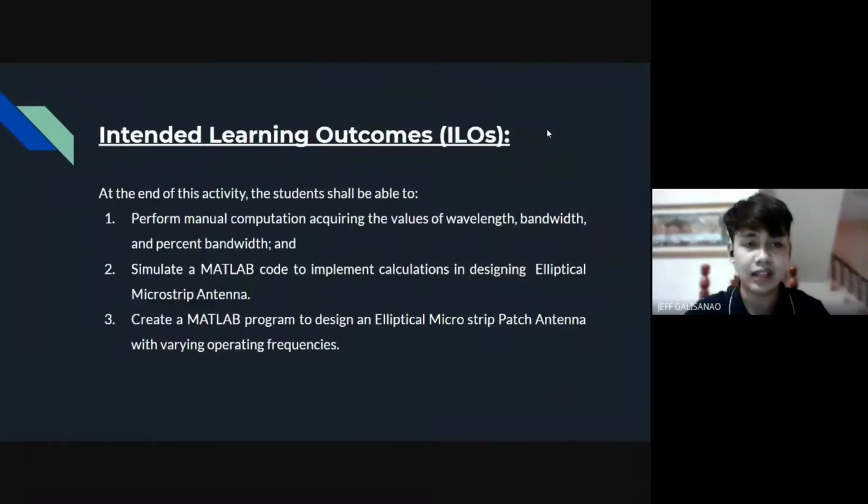And by the end of this activity, the student shall be able to perform manual computation acquiring the values of wavelength, bandwidth, and percent bandwidth, and simulate a MATLAB code to implement calculations in designing elliptical microstrip antenna, and create a MATLAB program to design an elliptical microstrip patch antenna with varying operating frequencies.